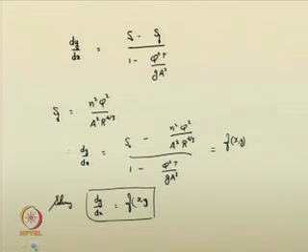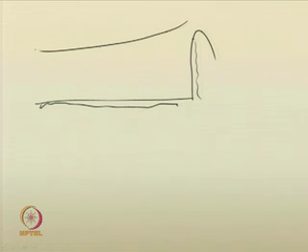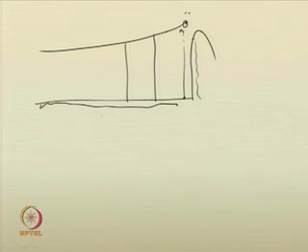In the RK method, what you are doing is that, say the entire reach, if this is the reach of the channel, say some dam is constructed here, some gradually varied flow profile is occurring, and if this is your control section, then keeping this as the known value, we are now discretizing the entire stretch or entire reach into small reaches, say maybe of del x length. Del x may be uniform or it may be changing.